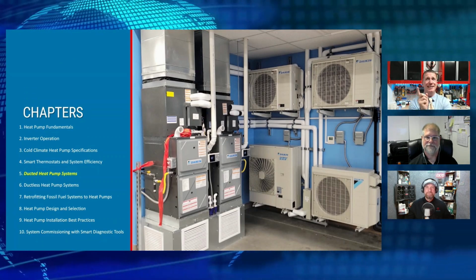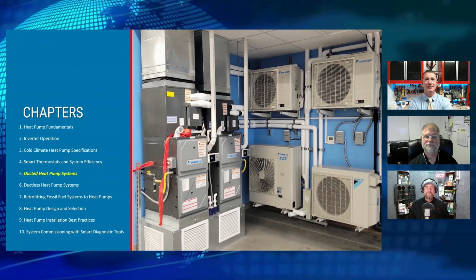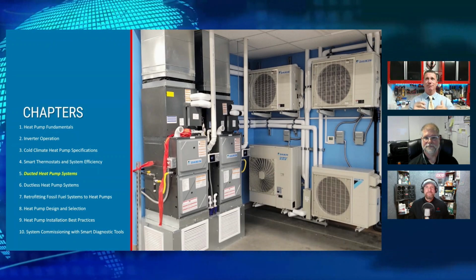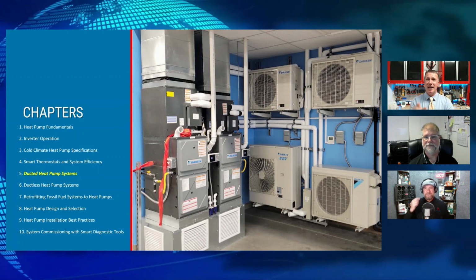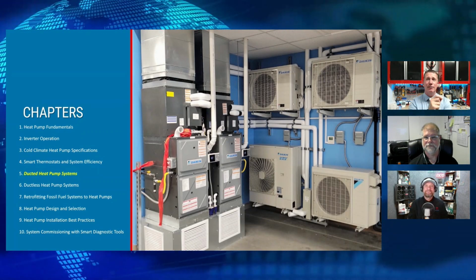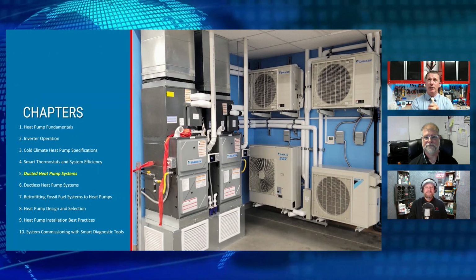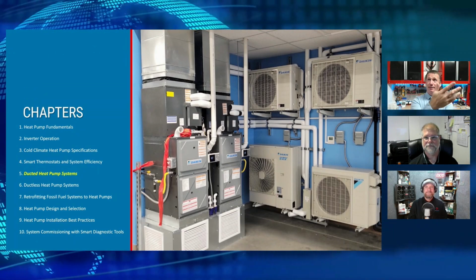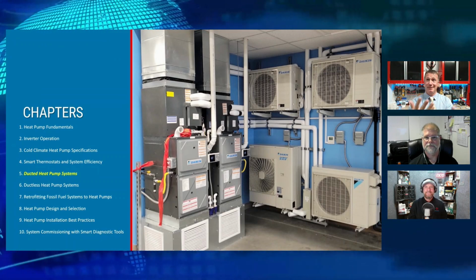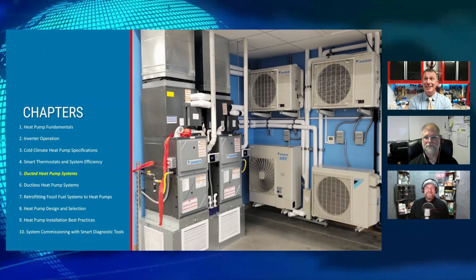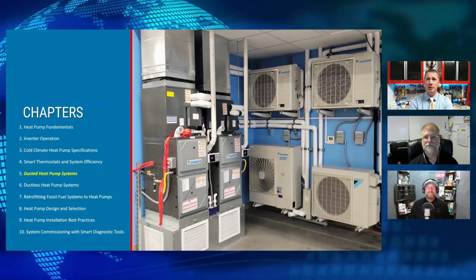And here's the thing that many contractors forget about when we start talking about variable capacity systems. Okay, so David, let's assume that I've got a newly installed inverter-driven system, and I haven't paid as much attention to airflow as I should, and so I've got poor airflow across the evaporator. What is a primary driving force for an inverter from that outdoor unit? Think about superheat, right? A lot of our units are being driven by superheat and compressor discharge temperature.